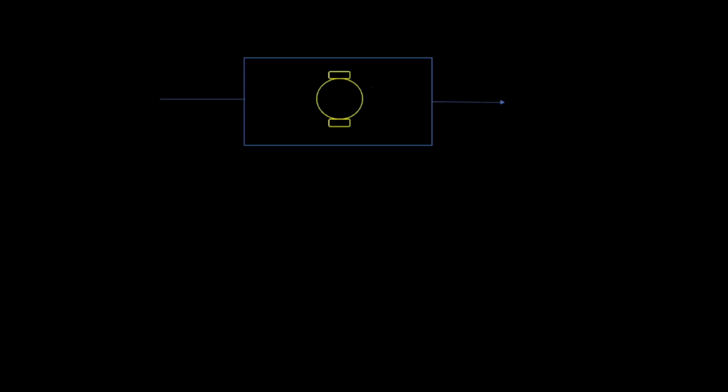Here we consider u as input, and we approximate that we get some state estimate from, let's say, GPS. Throughout we will be considering a GPS, but we can get it from any of odometer, IMU. We can use them considering what sensors we have on the robot. But for example, GPS might not have that much frequency. It might have a low frequency, or it might have a lot of noise, as might another sensor like a gyroscope. So what will we do?